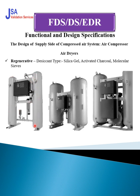Suppose the air is going like this, and then goes to the receiver. Here a small amount of this dry air will go into this chamber and then be exhausted from here. The moisture that is in this activated charcoal or silica gel will be dried off with this air, because the air will become humid and then be expelled.